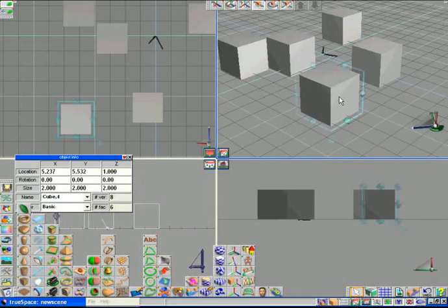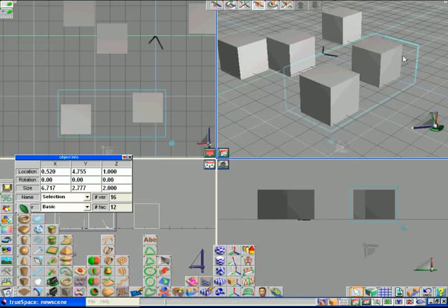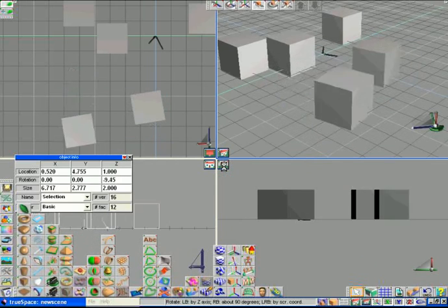Clicking on an object selects it. Clicking on another object unselects the first one and selects the second one. I'm going to click on this ball to get rid of some of those extra diamonds located around the selection boundary. To select multiple objects, you need to hold the Control key and then select your second object. You notice now that I have 2 objects selected because the bounding box is surrounding both objects. Located here, it's a little bit easier to see. Now when we use our manipulation tool, we're actually manipulating both objects,